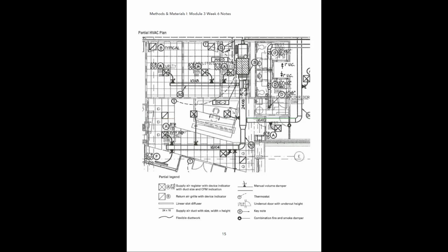All right, then once that air handling unit processes the air, it pushes it out through the ductwork. If you look at this ductwork here, the ductwork is indicated by these double lines, these thick, bold lines, and it's pushing it out through a main duct. The main duct is always going to be the largest, so this entire duct structure is laid out like a tree. You can think of this first duct as the trunk, and then we have all the branches coming off of it, and they're going to be progressively smaller the further they move away from the main air handling unit in the system.